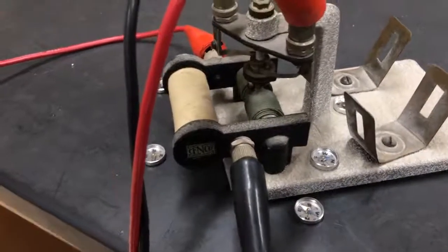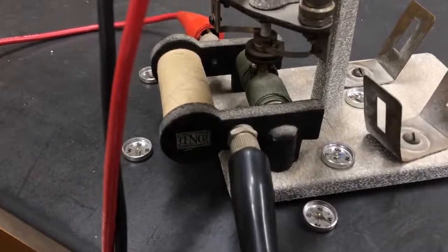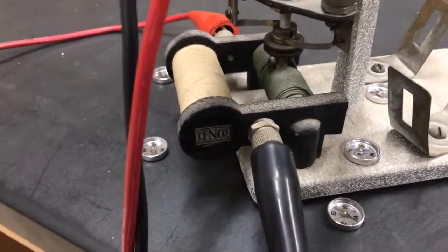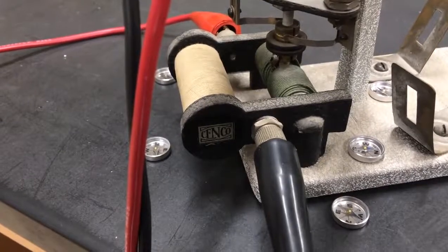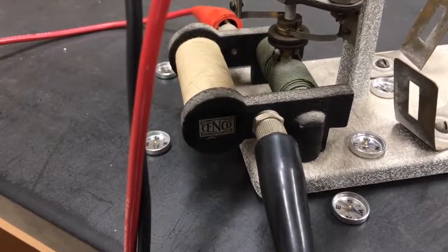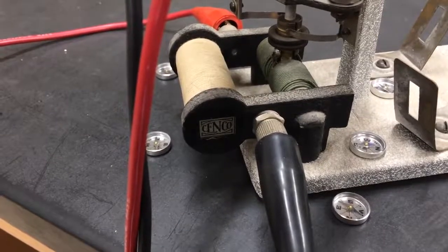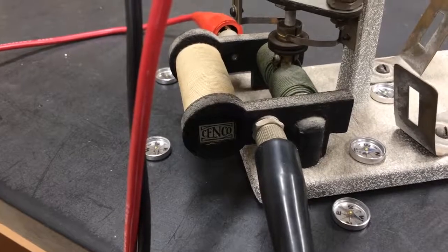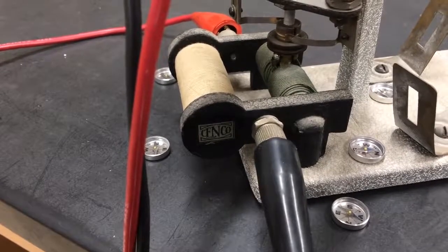So remember, the problem with DC motors is the current never switches direction. So if I was going to do the right-hand rule in this case, for argument's sake, let's say the left side of that green coil, the current is heading upwards. The imaginary positive charges are pointing towards the ceiling. In other words, it's rotating clockwise from our perspective.